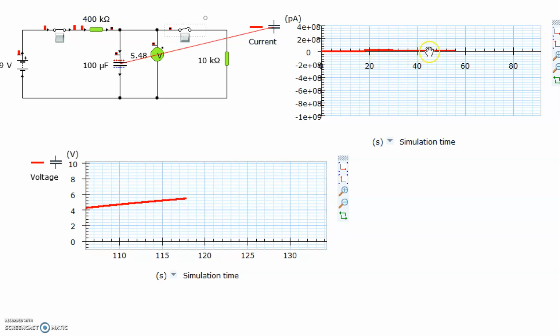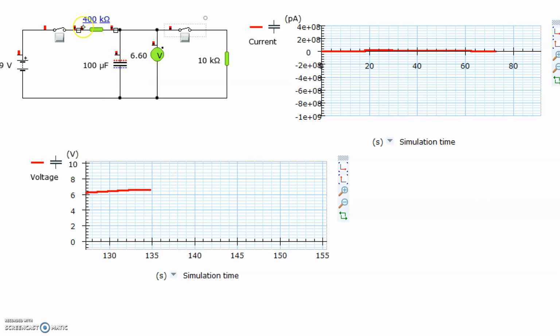The current is very, very slow. That's because the resistance is so high, the resistor is actually opposing the current flow into the capacitor, the charge rate, and the voltage is climbing up really, really slowly. So we'll just hold that there. Obviously, make that 10k much quicker.